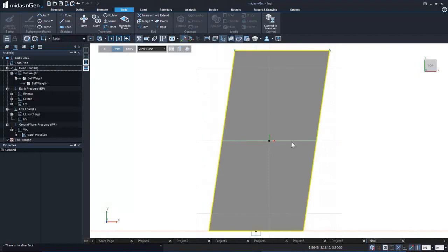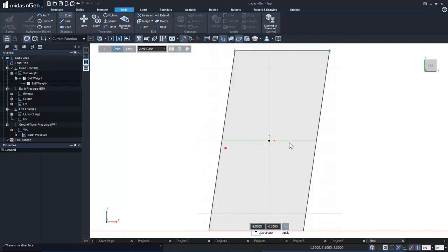And on this line, I have calculated how the point loading is going to come. Or you can have those 4 lines created on your box culvert itself and then apply the loading using points, or you can apply the loading using UDL on the line. So right now I have the information regarding a point load, like 2 point loads on my line.